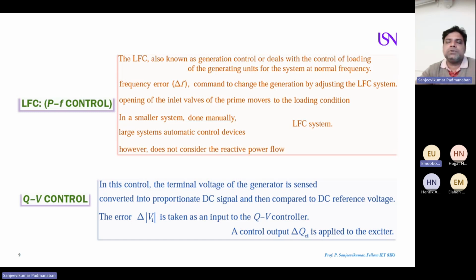Yes, as you know, the basic characteristic of your synchronous generator, which is not available in your doubly-fed induction generator, is that by controlling the excitation, by controlling the DC applied to your synchronous machine, you can make your synchronous machine work in three different modes or three different power factors: leading power factor, lagging power factor, or unity power factor.